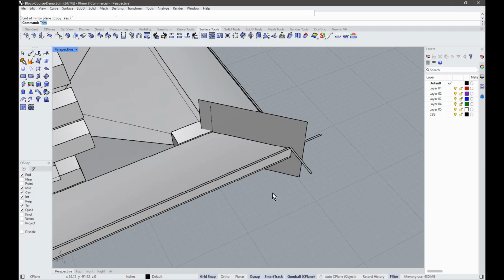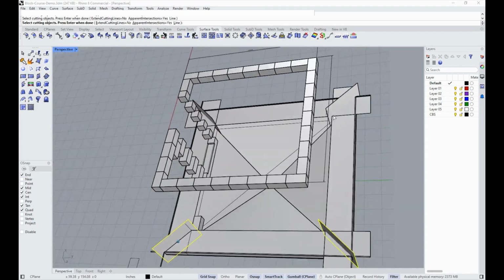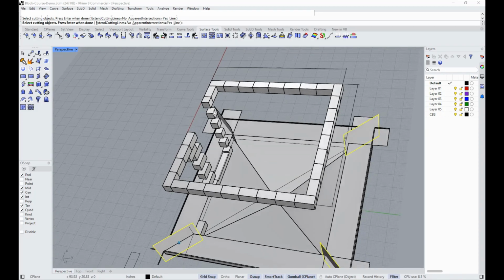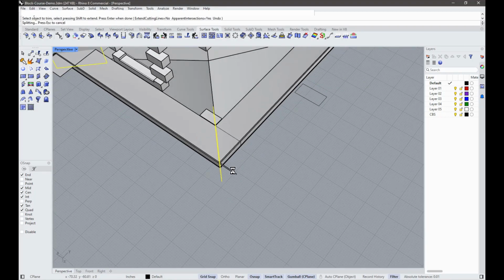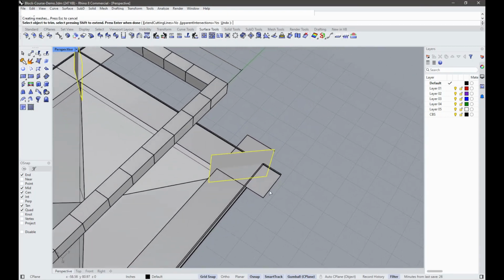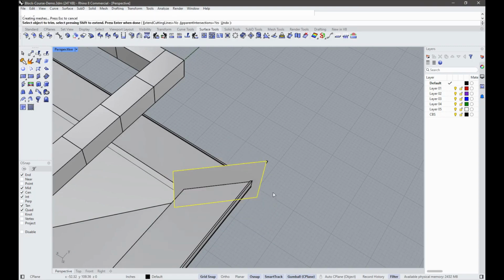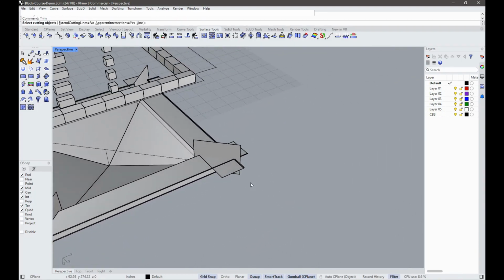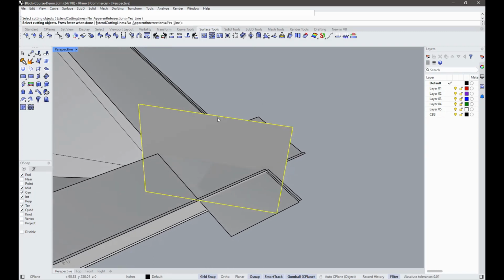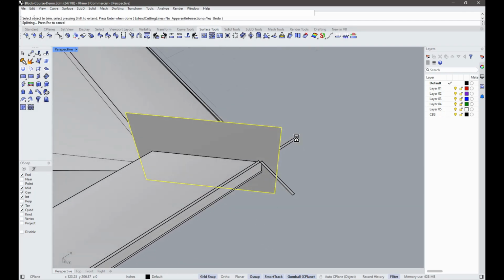So now we can do a trim. And we'll just grab those trim sheets again, so I can do everything in one pass. Let's see here. The command is you click on your trim sheets first, then you right click, and then you click on the trim. I'll show that here just so you see how it's going. So right click again to trim. I want this sheet to be my trimming surface, and then what do you want to trim? It's a right click, and that will let you select these pieces.